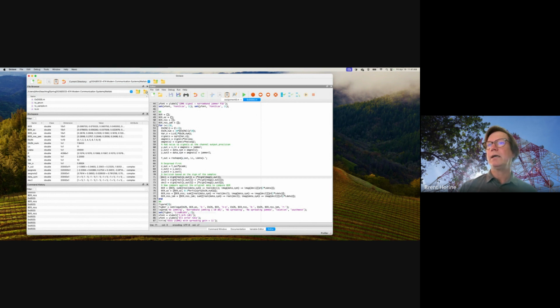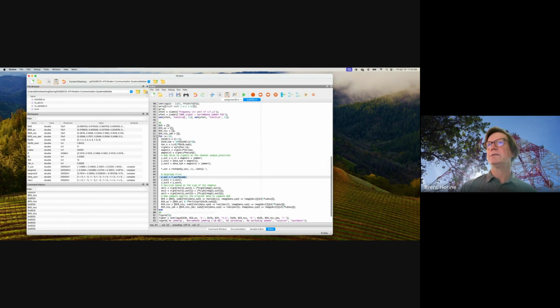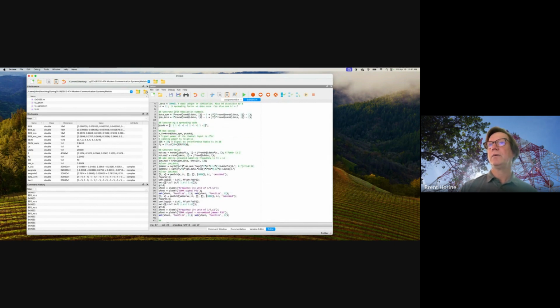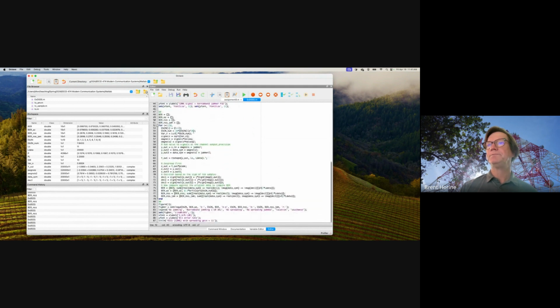And then there's some despreading here, which can be done just by multiplying by this P code that we have up here. And then there's some decisions that go on. Actually, it's just this one up here. So this decision will take these things and look at the sign. Since it's just QPSK, we just need to see, is it above or below the real axis?